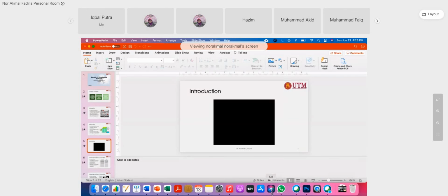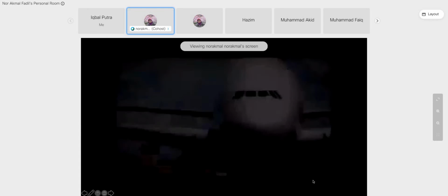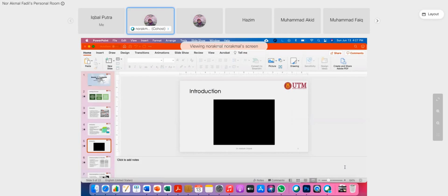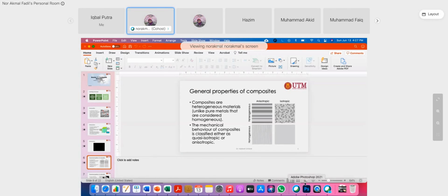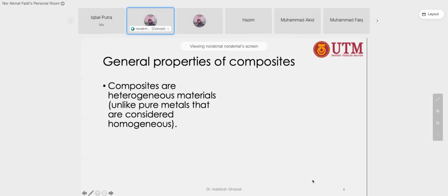As individual materials, the glass itself is very brittle and weak, but in the form of fiberglass it provides strength and eliminates the brittleness. Why? Because the brittleness has been covered by the properties of the matrix. Basically, the matrix materials we choose are materials that can absorb energy during the impact load.